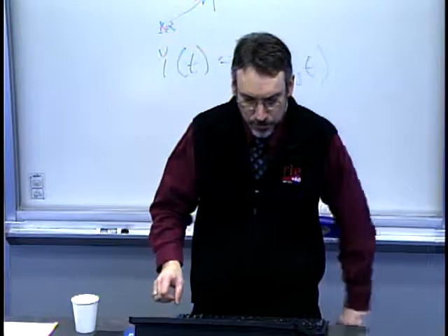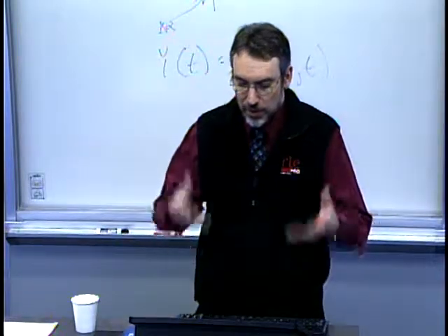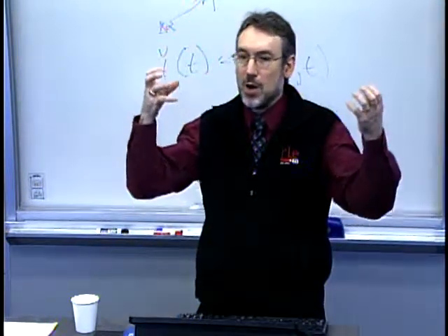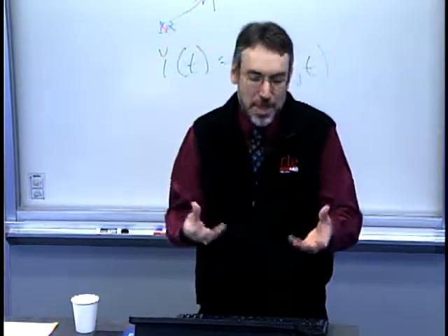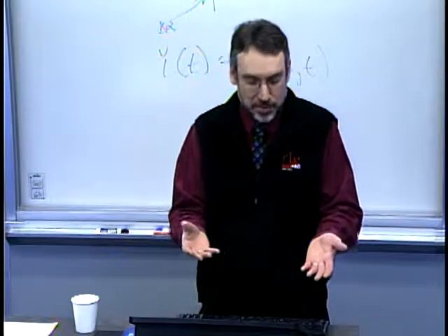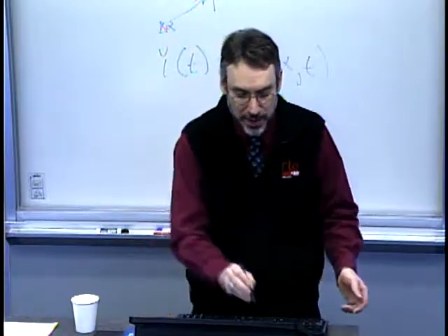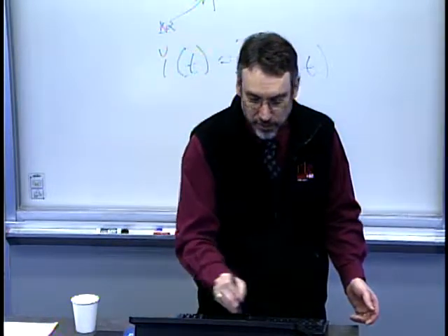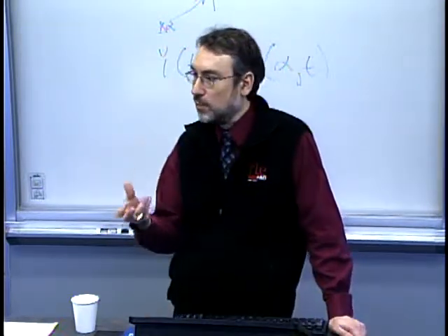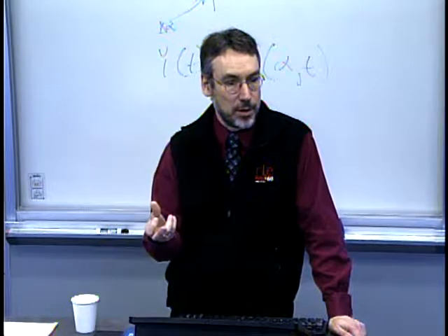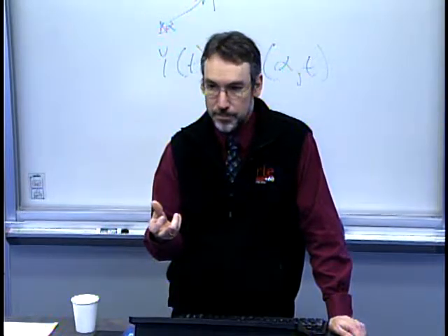So certainly, just to highlight a couple of the things Alicia mentioned. One here is very often we are also interested in within part variation. So assuming that maybe they all really were supposed to have the same dimension, then this spread here is very different than this spread here. So characterization of within part variation may be very important in understanding that.